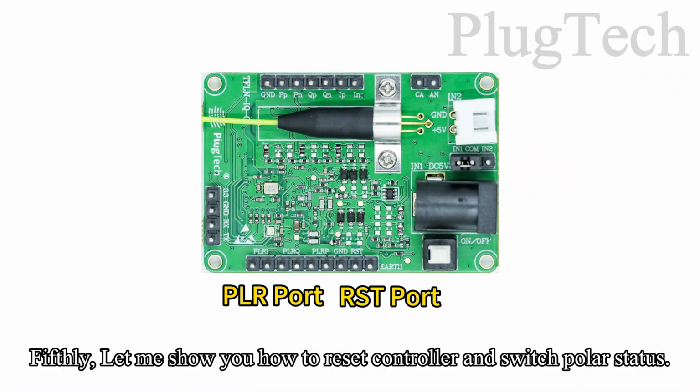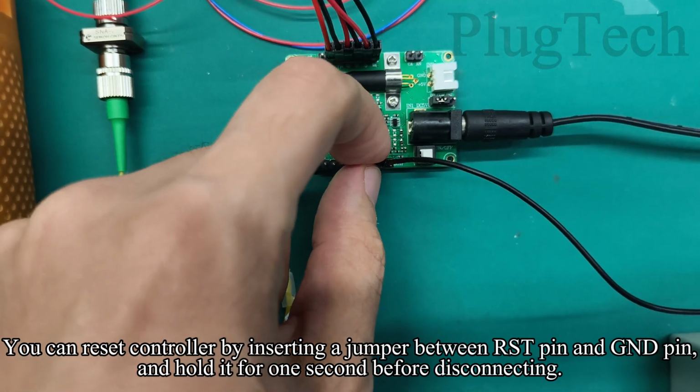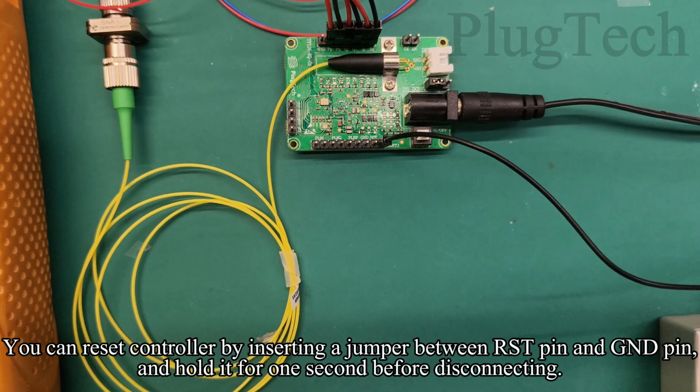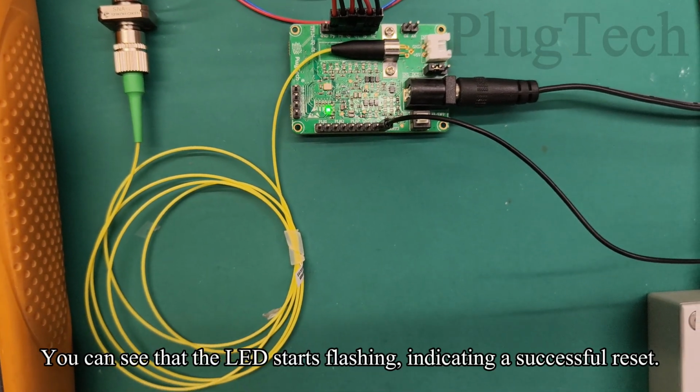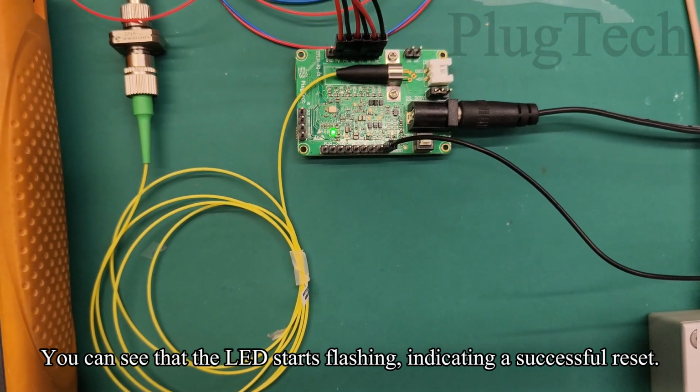Fifthly, let me show you how to reset the controller and switch polar status. You can reset the controller by inserting a jumper between the ST pin and GND pin and holding it for 1 second before disconnecting. You can see that the LED starts flashing, indicating a successful reset.